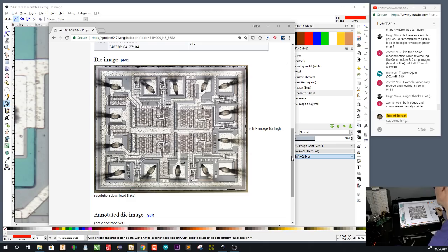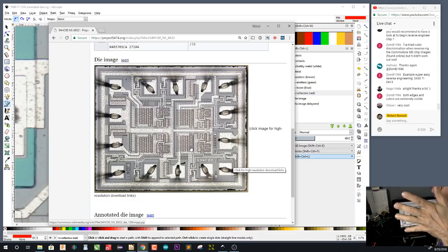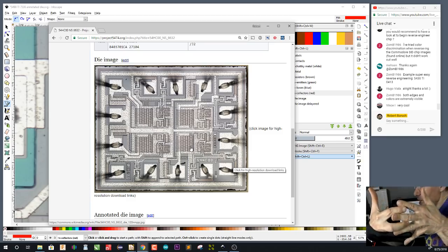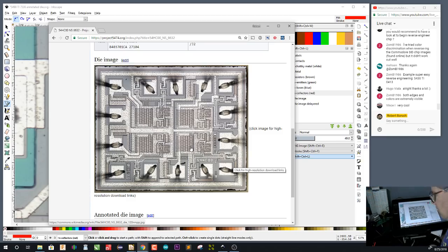Yeah, you can see that the structure is really, really simple to look at. And if you actually download this and zoom in, you'll see that these complicated structures in the middle, that's actually just a single high power transistor. Basically what you have is the drain and the source sort of interdigitated like this. So that's why it looks so complicated.